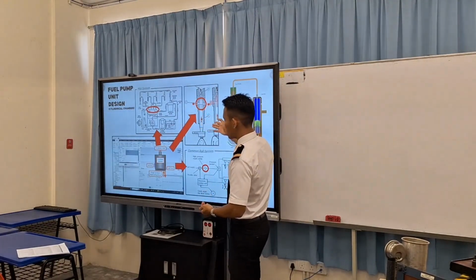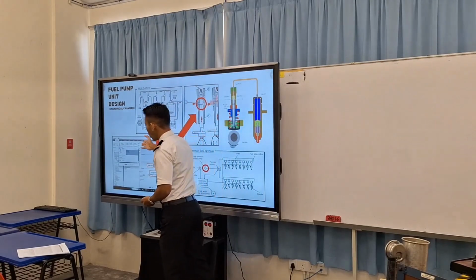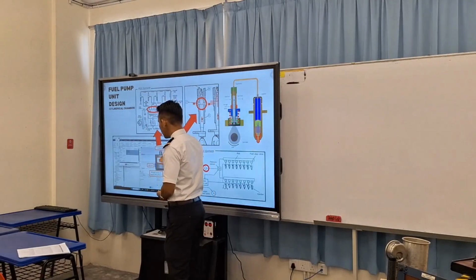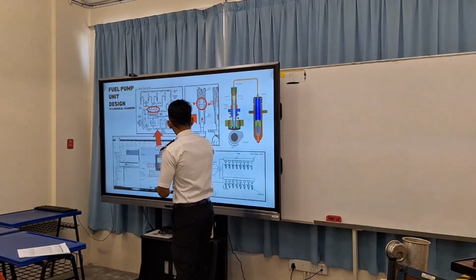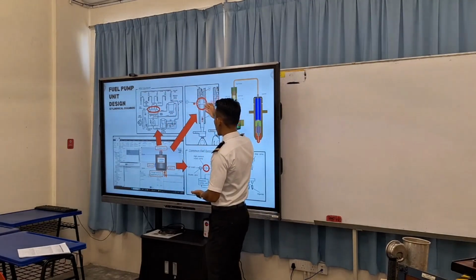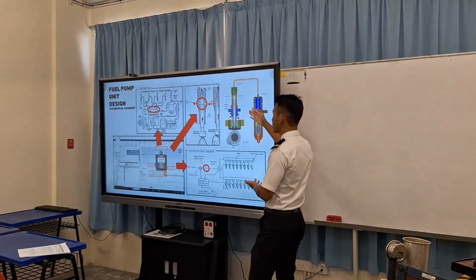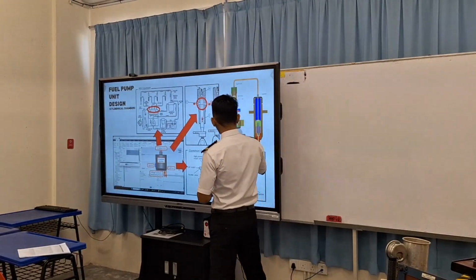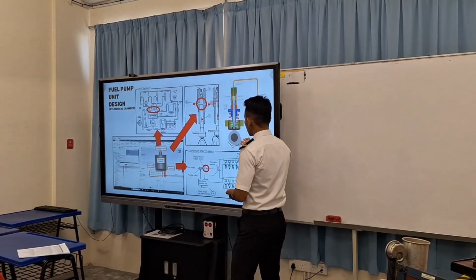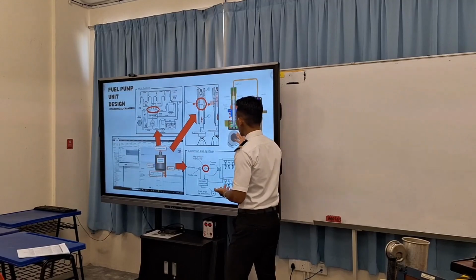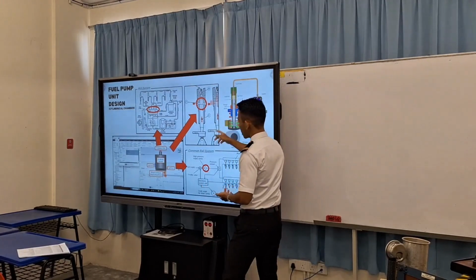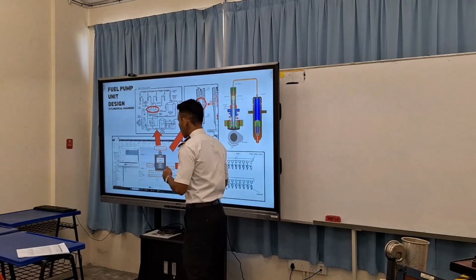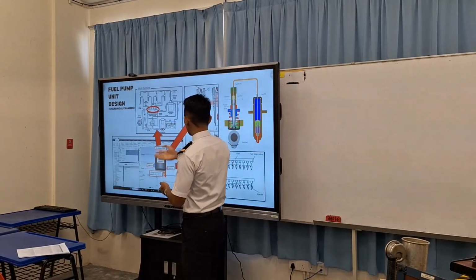For the solver setup, this is the interface of the software. Right here, this is the in-cylinder chamber. We can compare with this one. This is the electrical pump, and this animation will give you an idea of how the fuel pump operates. As the camera is rotating, at the right angle, you will push up the plunger and the barrels. This plunger and barrels, with this reciprocating motion, will cause the delivery of the fuel into the system.